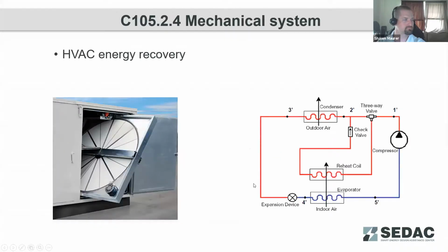Next thing that we're going to be looking at is an energy wheel. It's probably the most common system that we see for energy recovery systems. Also, for energy recovery systems, hot gas reheat qualifies as an energy recovery system. However, hot gas bypass does not.